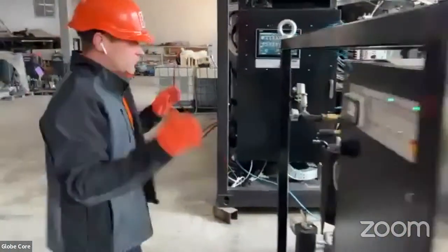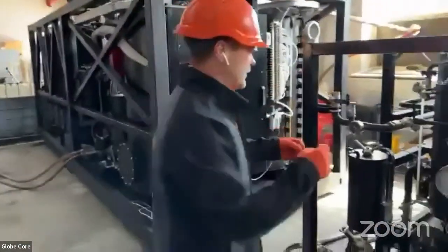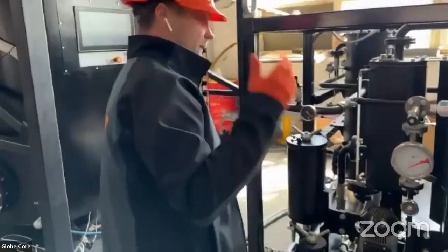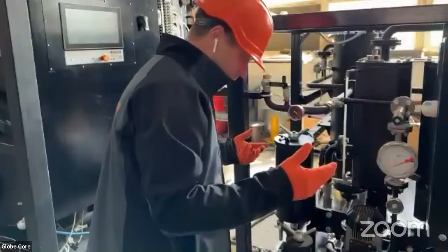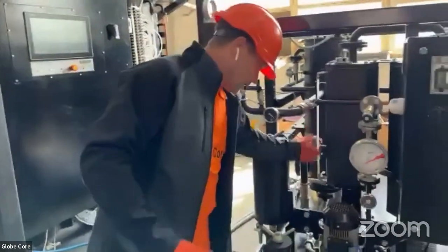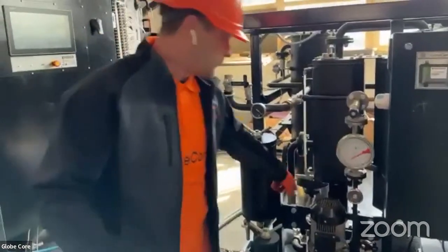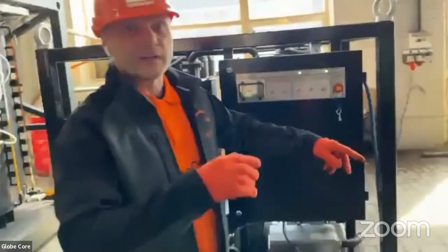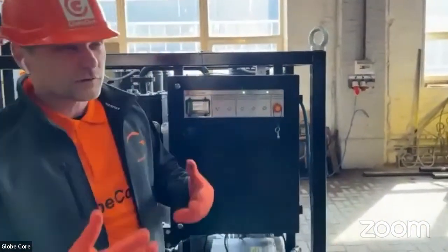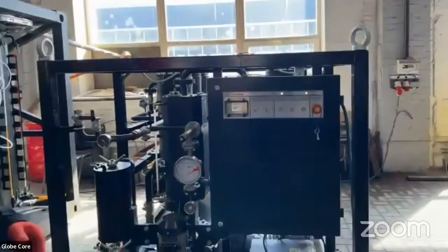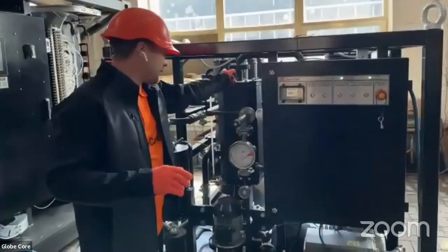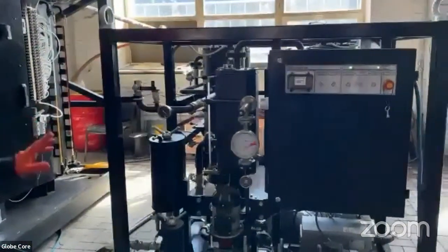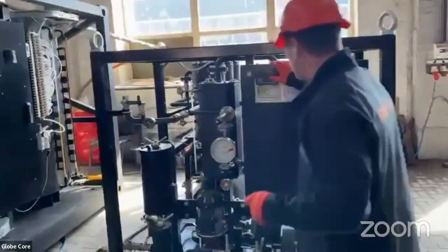So regeneration, just press oil through the columns. Reactivation, ignite, and we burn the sorbent. The air is supplied by the vacuum pump. We try to save as much oil as possible by passing it from the intermediate tank to the external tank. By the way, this product can be regenerated again, so the losses are really small. Okay, and the combustion products are refined in the charcoal filter. Actually, this is all.